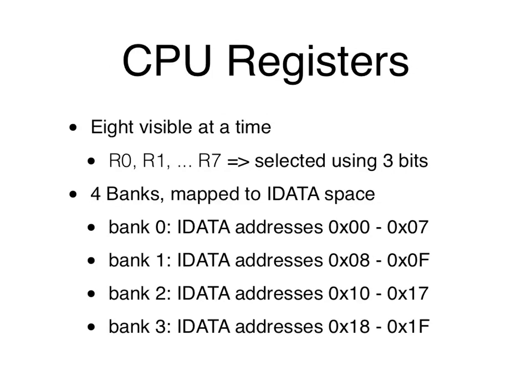Okay, so now let's take a look at CPU registers, or R0 through R7. Now, there are 8 of them, right? So that means to pick one of them, it takes 3 bits, right? 2 to the power of 3 is 8. And these 3 bits are usually found inside your instruction, what we might call the instruction encoding.